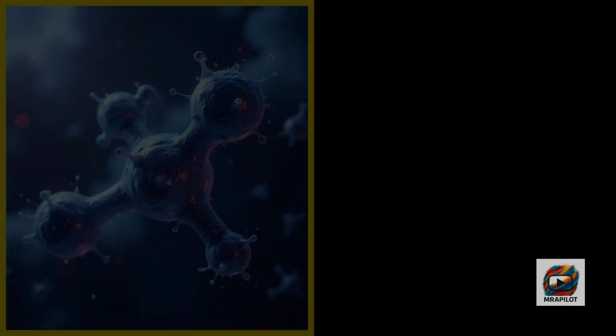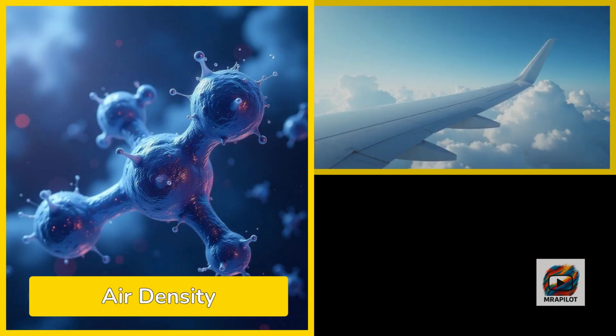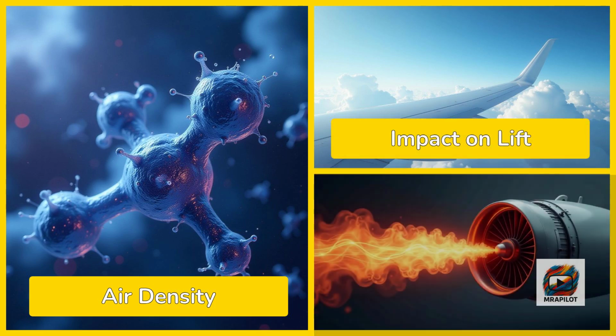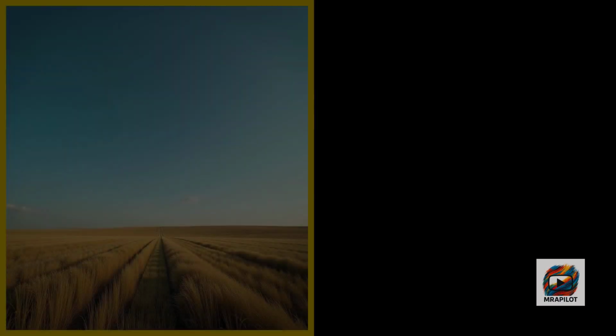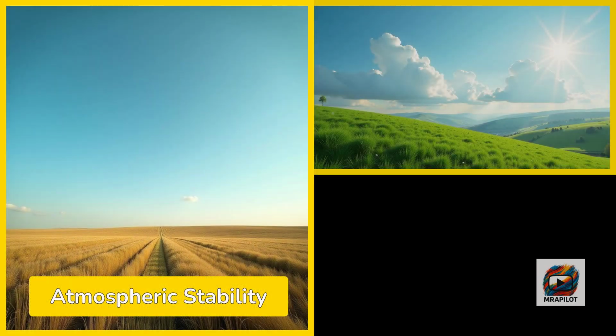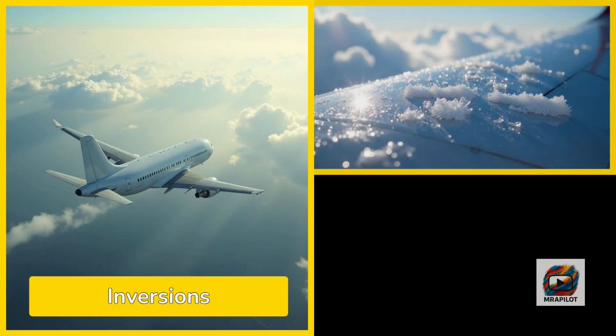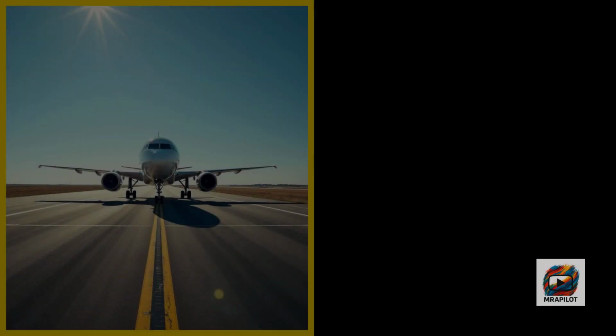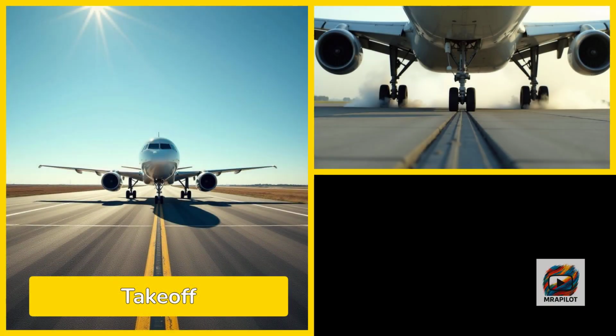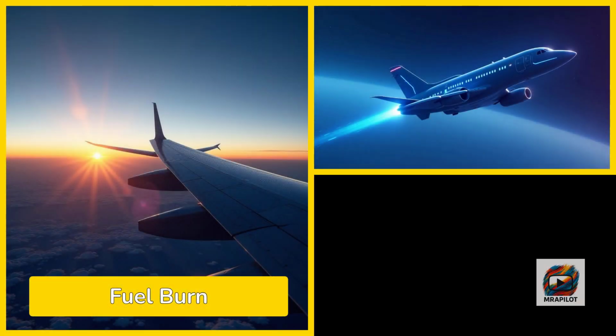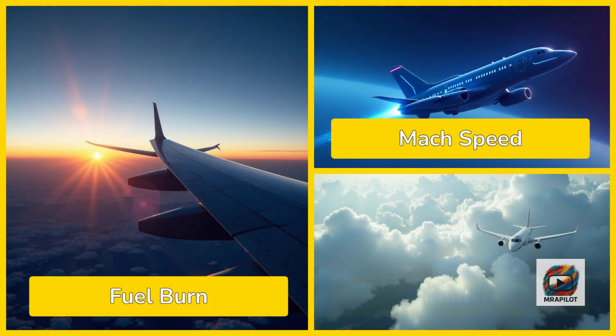Let's recap what we've learned. Temperature affects air density, lift, engine power, and aircraft performance. Lapse rates determine stability and cloud formation. Inversions and icing create operational challenges. Surface temperature matters for takeoff and landing. High-altitude temperature affects fuel burn, max speed, and turbulence.